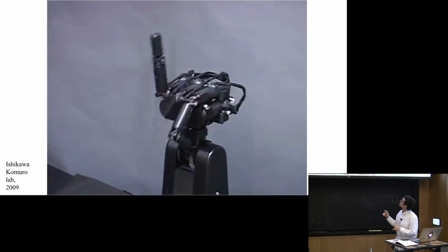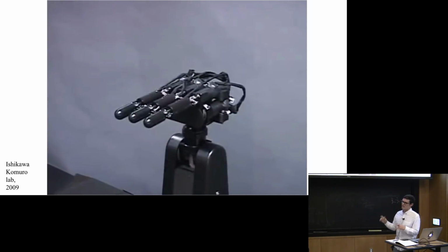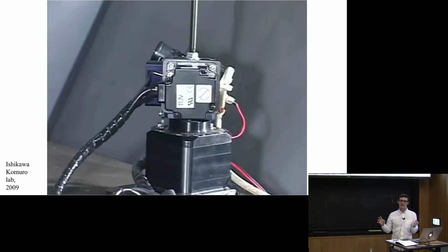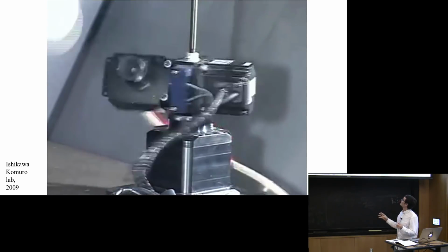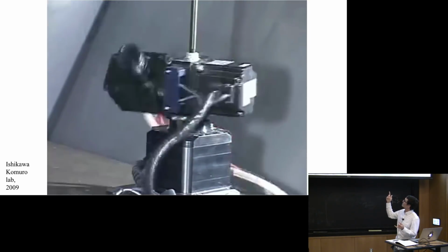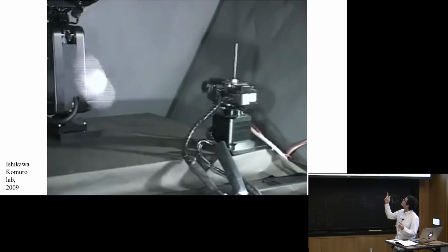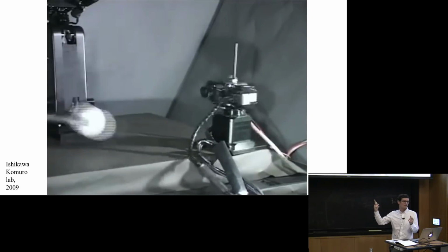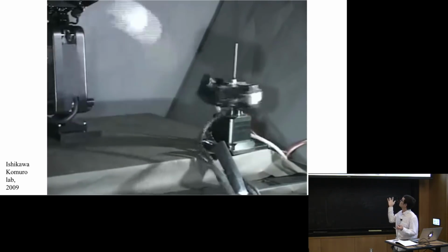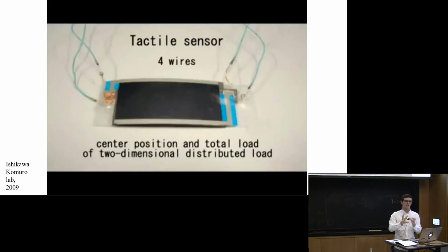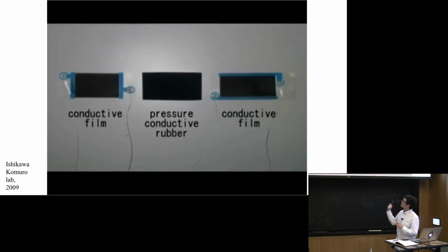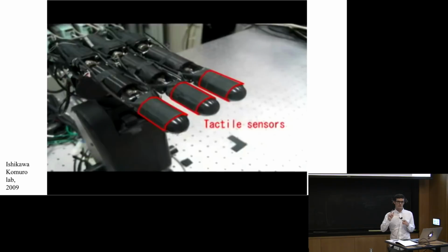It's an amazing overall systems engineering effort with this awesome hand. And then this is their camera setup. They've got an active gimbaled camera, where they can track at super high speed the thing that they're looking for. Now this type of computer vision pipeline is engineered to look for the thing that they know they're looking for. They also had tactile sensors in this setup, and they use them for real-time feedback.